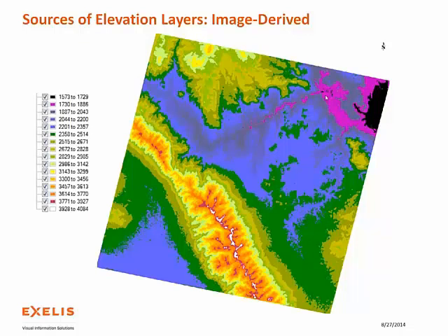And here's the actual DEM that was generated. So that was an ASTER scene. And the DEM input was the 15-meter pan bands. So that's the best resolution that we can get from the ASTER data, if we do some pan sharpening using those pan bands and extract the DEM from those. So this would be really suitable for a lot of applications that don't require very high accuracy DEM resolution.